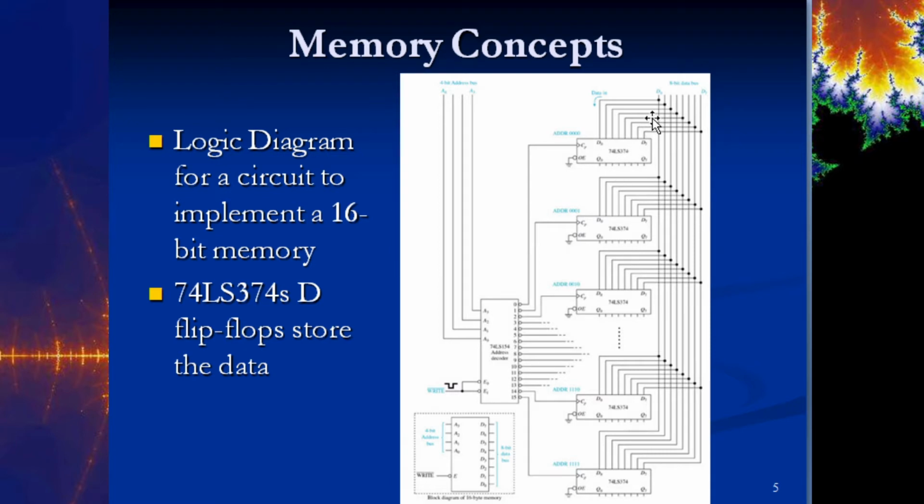That way you don't lose that data. Okay. So anyway, they're all connected here in a tri-state mode, and then it's only one of them that gets activated, right? So you can see here they all are connected via their clock pulse, and obviously this decodes it. It triggers one of these. The clock pulse gets triggered, and then it pulls in whatever's on the bus and locks it into the Q. Okay, but for this one down here, just because it didn't get written on this time, you still want it to maintain what its Q values are. And so that's why all these are in a tri-state position.